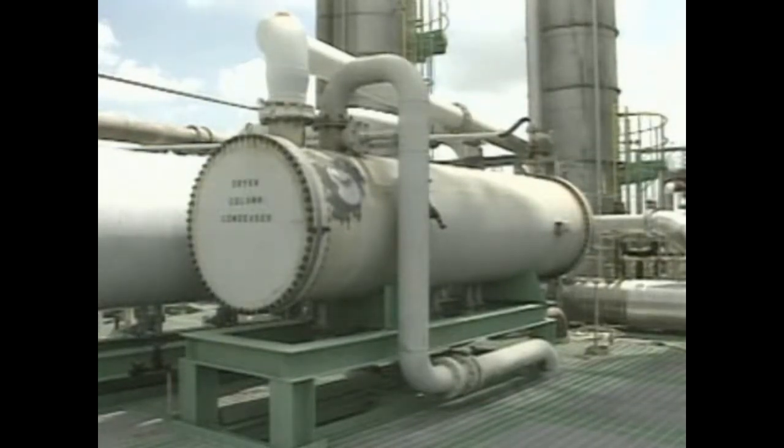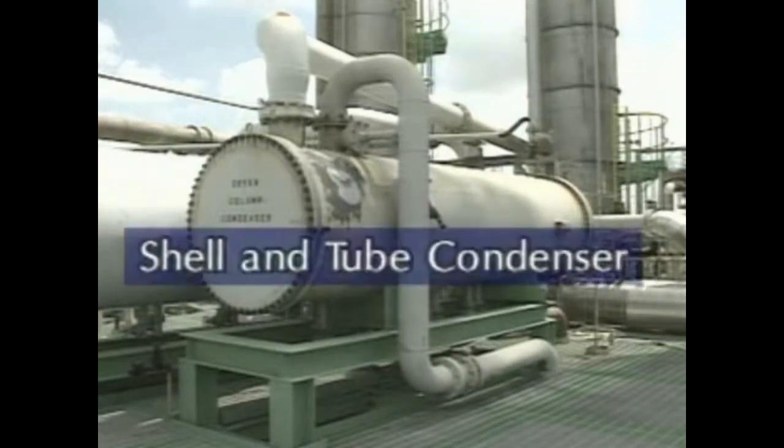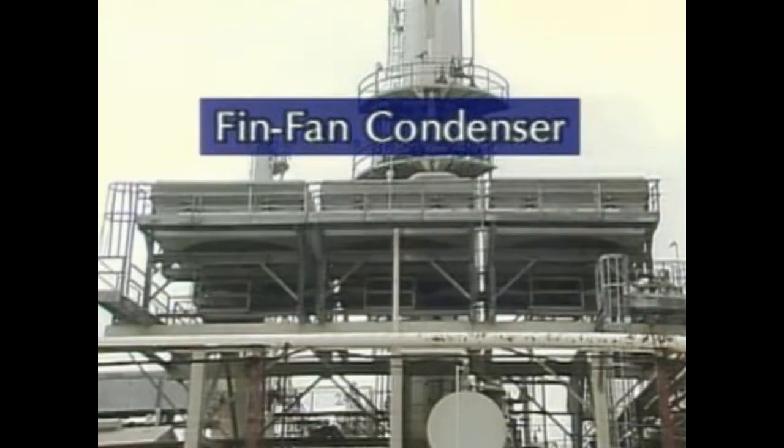In a distillation system, a condenser removes heat from the overhead vapor and turns the vapor back into a liquid. Two common types of condensers are water-cooled shell and tube condensers and air-cooled or fin fan condensers. Both types of condensers can experience problems. Many condenser problems are related to the cooling medium that flows through the condenser. These types of problems can ultimately affect the amount of cooling provided by the reflux.